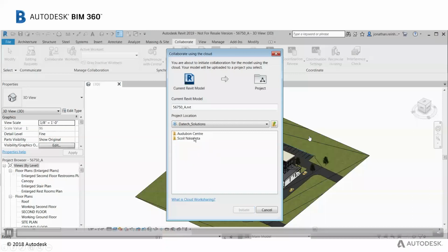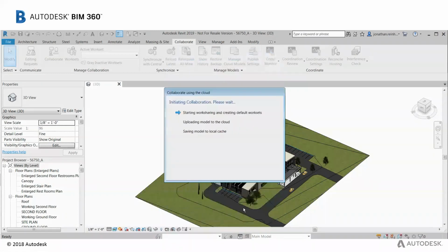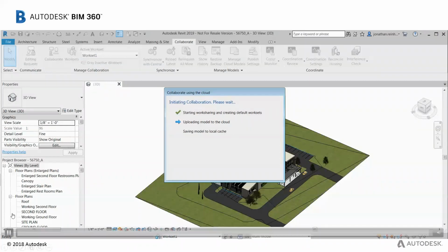So what I'm doing here is I'm selecting a folder within my BIM 360 environment. I'm selecting where I want to store that model. This is then going to allow me to retrieve that model either on site to be able to view the drawings attached to it, to be able to review any sort of design issue information attached to that 3D model. And you can just imagine the efficiency of this. So straight from a design environment in Revit and being pushed through up to the cloud. You might even have a guy on site that's waiting to pull this down off the cloud 5 minutes later. You're able to do that.